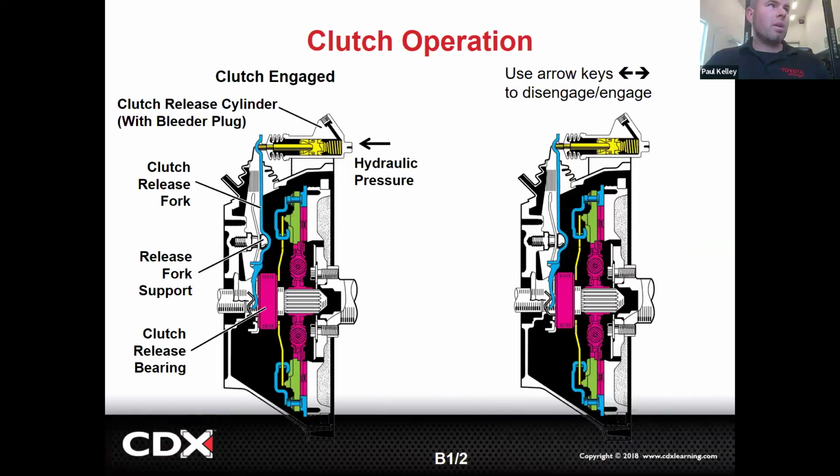And then we've already kind of talked about the clutch operation, but now that we're on hydraulics, I want to talk a little bit more in detail. So in this case, the engine's on the right. When we send hydraulic pressure, the slave cylinder receives the pressure and transmits it into motion. And this is going to expand and push on the fork. And that fork going to the left will pivot and it'll push the spring. See, this is the pivot, and it'll push the spring to the right using the release bearing, right? So that's pretty much the motion.